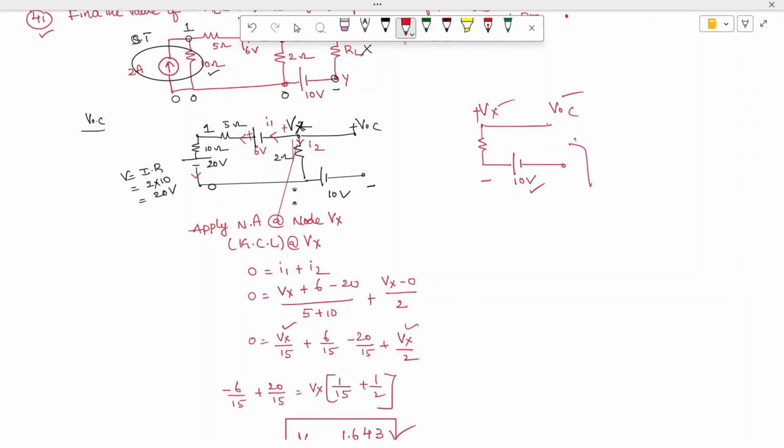So in order to do this, let us try to apply Kirchhoff's voltage law inside the loop to link all the voltages. Let's try to assume the current is flowing like this. Whenever the current is flowing, this is nothing but plus VOC, and the current is leaving, or the leaving polarity, minus Vx, and current is flowing like this, which is nothing but minus 10.